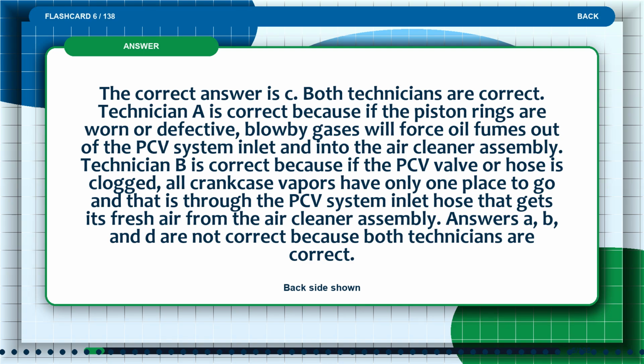The correct answer is C. Both technicians are correct. Technician A is correct because if the piston rings are worn or defective, blow-by gases will force oil fumes out of the PCV system inlet and into the air cleaner assembly.